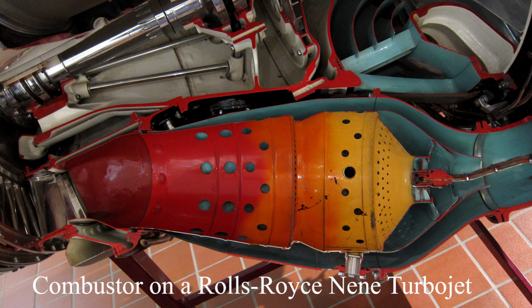The combustor must completely combust the fuel. Otherwise, the engine wastes the unburned fuel and creates unwanted emissions of unburned hydrocarbons, carbon monoxide or CO, and soot. There must be low pressure loss across the combustor. The turbine which the combustor feeds needs high pressure flow to operate efficiently. The flame or combustion must be held or contained inside of the combustor. If combustion happens further back in the engine, the turbine stages can easily be overheated and damaged.